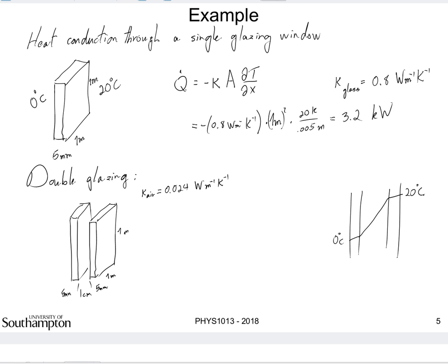We're going to be able to apply Fourier's law from there to there, and we're not going to be able to solve it yet because we don't know the temperature there. But we can apply it from there to there, and then we have a relation between these two temperatures, and we have it from there to there, and we have a relation between these two temperatures, and then we can shuffle things around, and we're going to be able to find a solution. Okay?